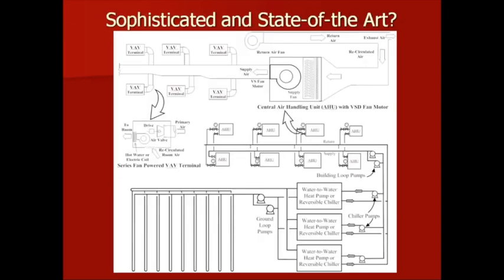And I won't make any bones about this. I have a hard time accepting why people will do this, but there are a lot of people going to, in this case, what's called a ground source heat pump system hooked to something that's quite popular in larger buildings in the U.S., variable air volume chilled water systems, where you have either a chiller, a reversible chiller, or water-to-water heat pumps hooked to air handlers, and the air handlers, of course, hooked to variable speed fans and terminals out in the field.